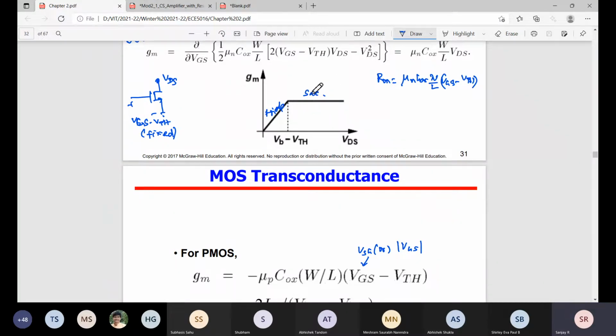We want more gain, which means more transconductance. Because what is transconductance? Applying gate voltage, we get current amplification. That's what GM into VGS. So the MOSFET is a voltage controlled current source. The output is a current. So that's what we are operating.